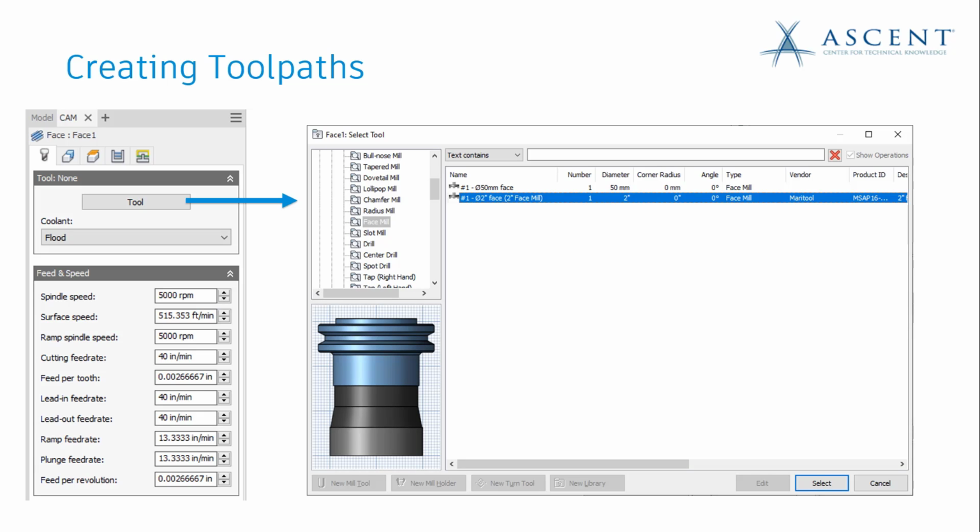To begin, when you're looking at this toolpath palette, you always define your tool first, the first tab that's available, and this is simply done by selecting the tool from a library. I don't have time to get into all of the tool library specifics. There's definitely more explanation in my handout. At a high level, what you basically do is select a tool from the standard Inventor library or custom library that you might have set up for your company, and you want to select the tool that would be best matched for your operation.